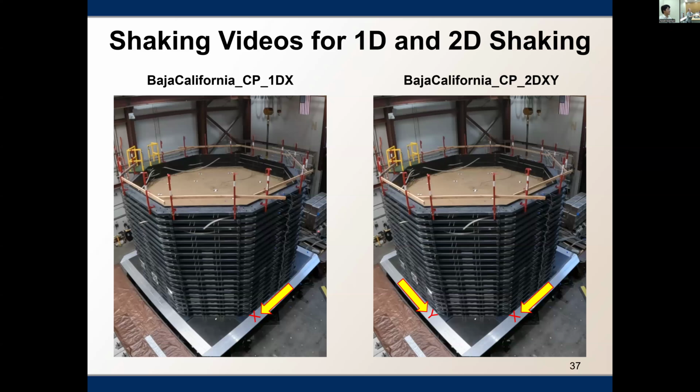On a similar note for you or Reza, are there plans to have two different soil types, like sand with a softer clay at the top, or is it going to be pretty homogeneous for future testing? For future tests, we are still using the same soil. Because if we are looking at soil-structure interaction, it's better to have the same soil and then check the response of the structure. But maybe in future tests we could have different layers. For the purpose of this study, we just require uniform soil, and it's much easier to make.